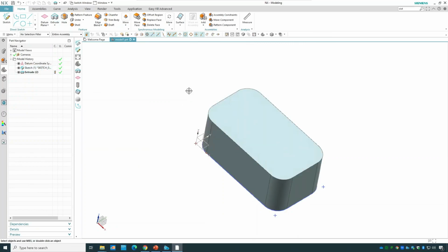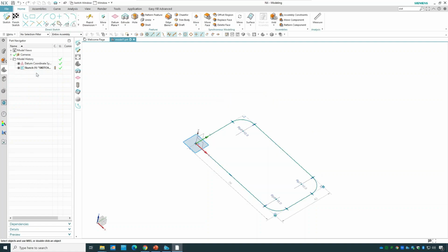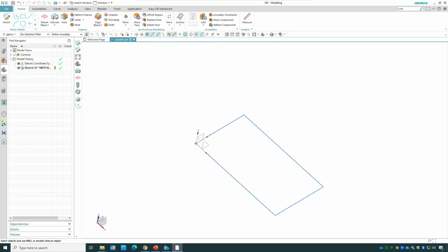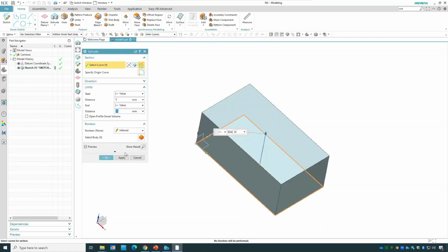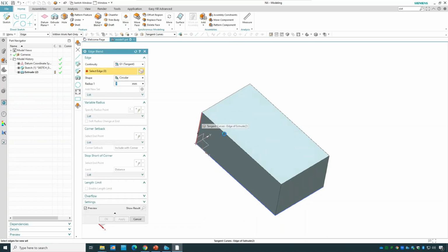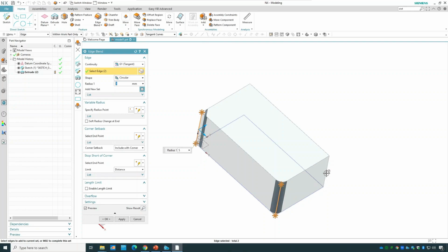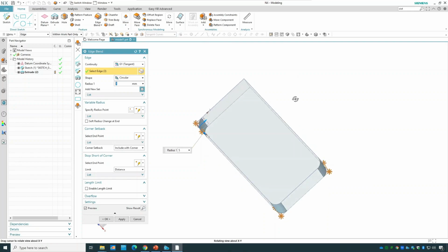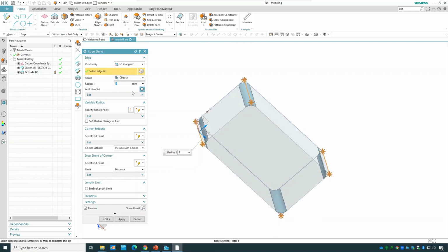And you can see I still got the fillet through the edge. But again, in case I haven't done it, let me go back to the sketch. Let me do a Control Z, get rid of the fillets. What I could do is extrude this one, and then come to the edge blend and apply the fillet with a value of 10.